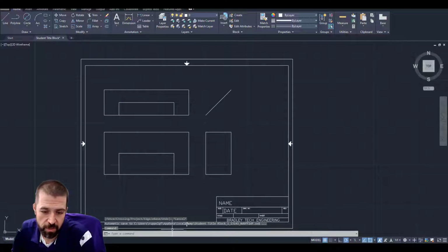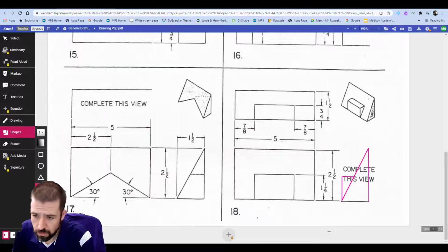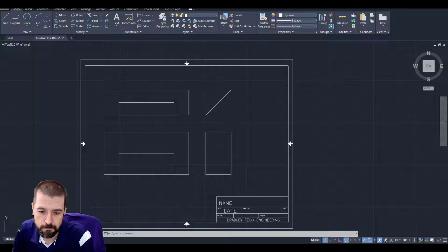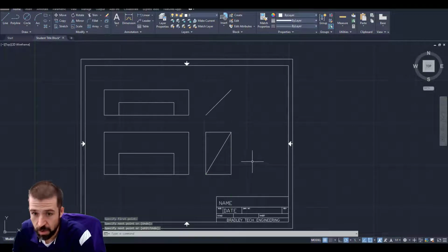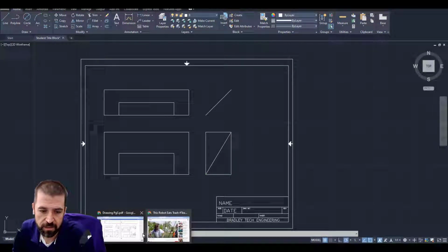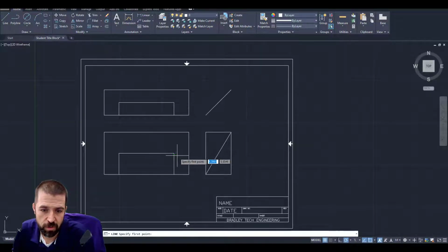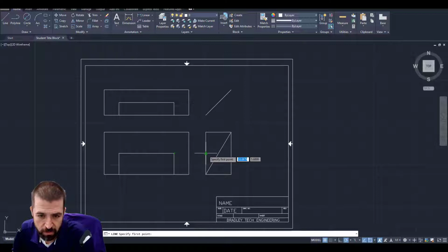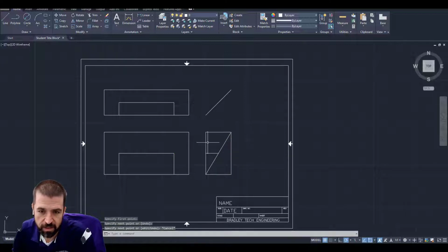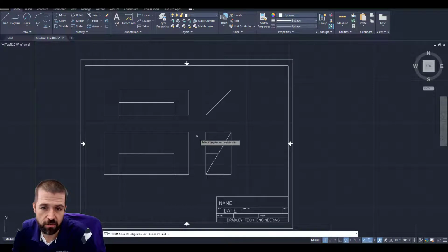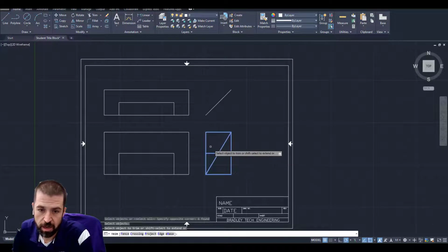Alright, now let's take a look at my left side view. I start by creating one triangle. So my line tool from here coming straight up. But in order to get that other triangle, the smaller one, I'm copying from this front view rectangle across. I'm going to take my line tool, hover over it, and simply drag my cursor to create that secondary triangle. Now I can use my trim and trim out so that all I'm left with is that triangle.